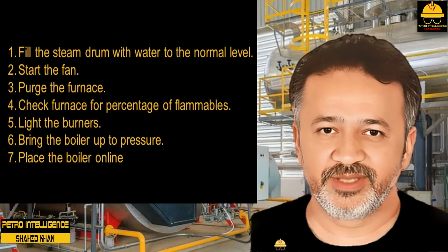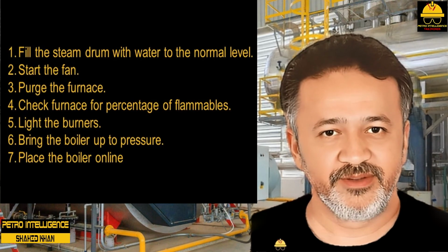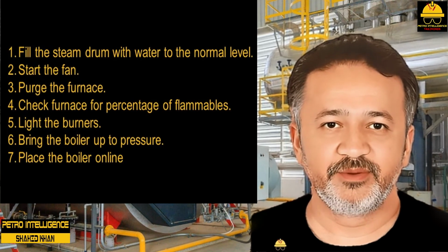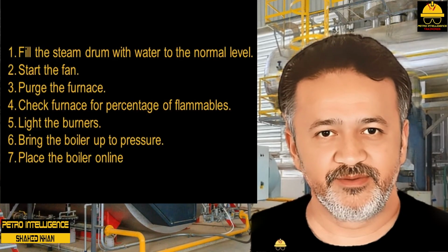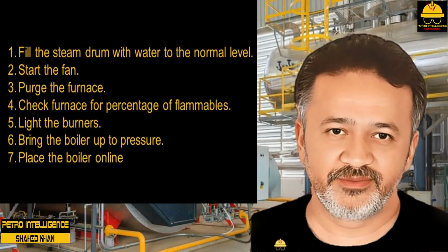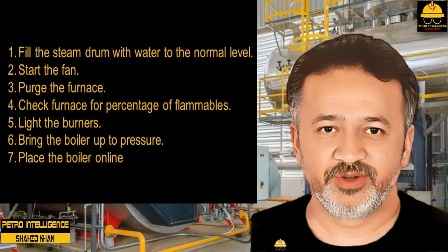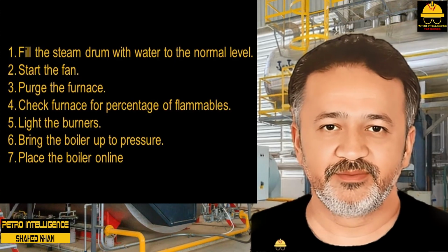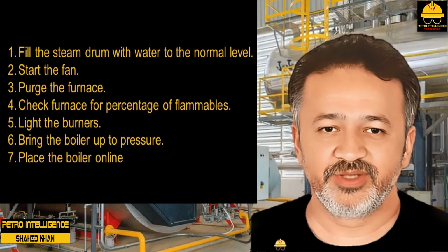Typical boiler problems include tube rupture, soot buildup in superheater and economizer tubes, loss of water flow, flame impingement (frequent or sustained contact between flame and tubes), scale, impurities in steam or water, flame failure, and improper water level. It is usually the operator's responsibility to control water and steam flow rates and temperatures and water level in the boiler. The operator also checks for smoke and checks burner and flame pattern.